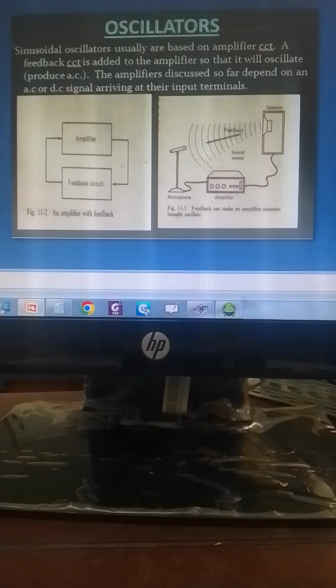So you have an input here. This input goes through the amplifier to the speakers. Then that feedback sound comes again back through the microphone. That is the feedback signal that we have. This one here is also a feedback. It is just a replica of what is transpiring here, because this is in circuit diagram, but in real life this is what transpires. When you hear those squeals, it is feedback entering through the amplifier again.